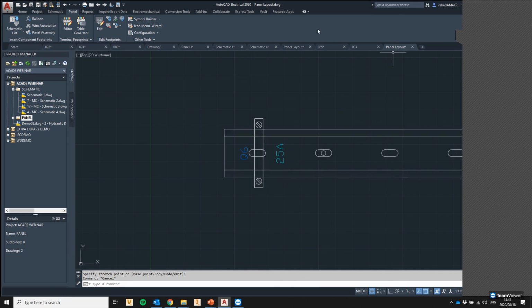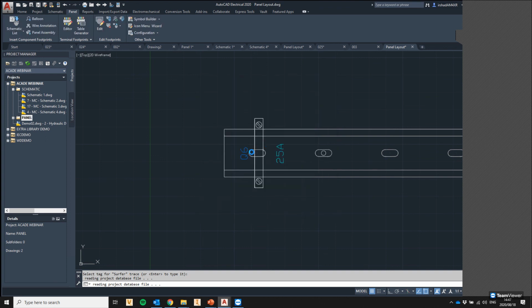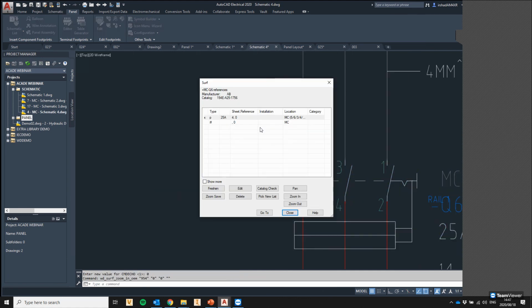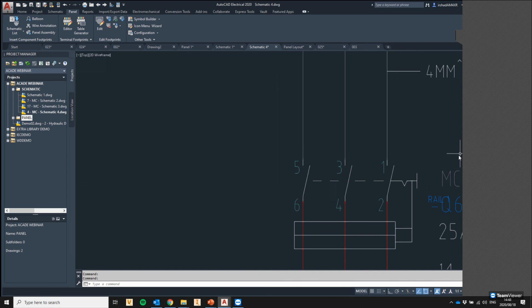And of course, we have the little surf tool, which helps us identify things. So if you look up there, there's a little button. We can maybe surf for this component. It'll tell us all the different installations where it is, and you can click on it. For example, I want to go there. It tells you where the reference is. I can say go to that one. It's just going to ask me to save here, and then tell me exactly where it's coming from. It points me in the direction of the right one, which is why it can be very, very useful.